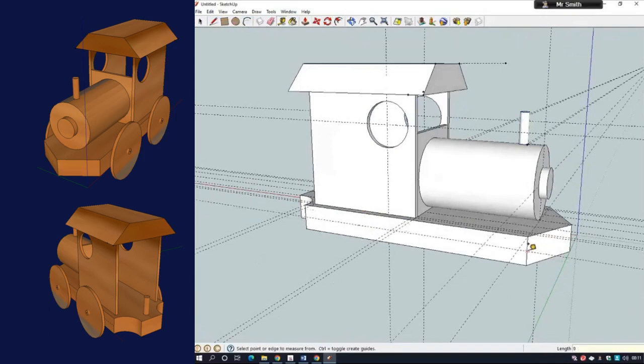Now, I'm going to work on the wheels. So I've measured down 9 millimeters, which is half that distance. I'm going to measure it 40 millimeters along, where the center of the wheel is going to go. So 40 millimeters. Then I'm going to measure back again 30 millimeters and draw my wheel in that place. And you see it was green because it's been drawn in this axis. So again, 40, back again, 30.